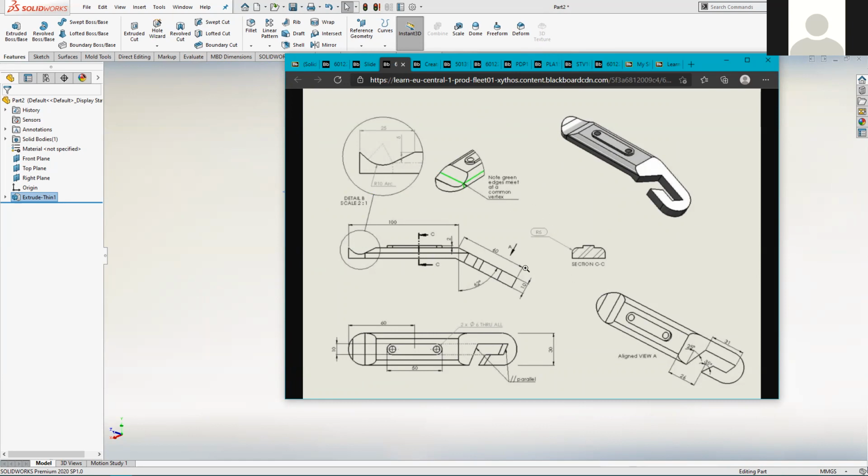So there's a little bit of thought that has to be put in at this point as to what the wisest order of features is going to be. How is it best to create them? Which one is it best to create first? Which one second, third, fourth? And there are certain paths down which you realize that you've created a feature and you've created it in error. It needs another feature to go in before it.